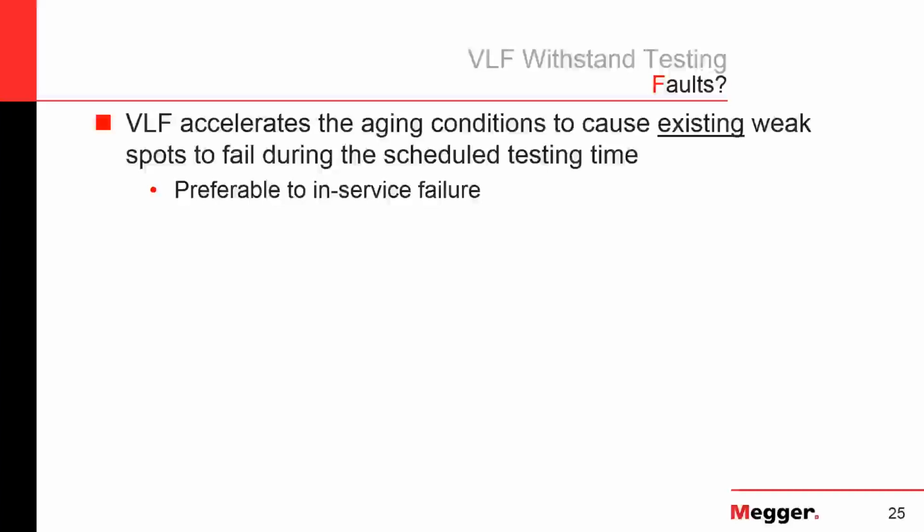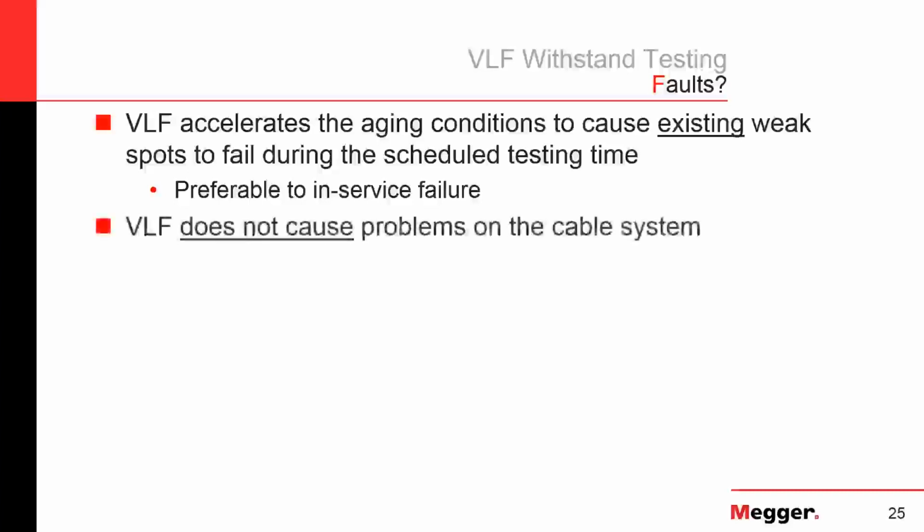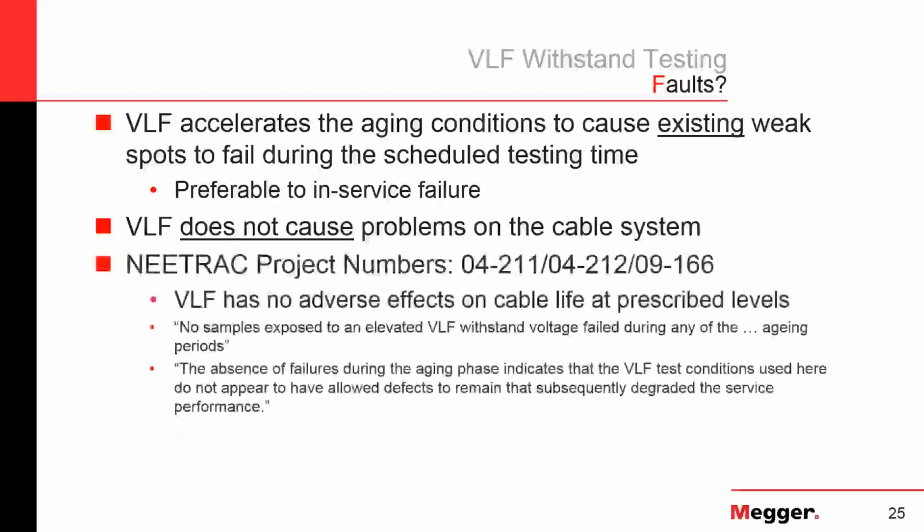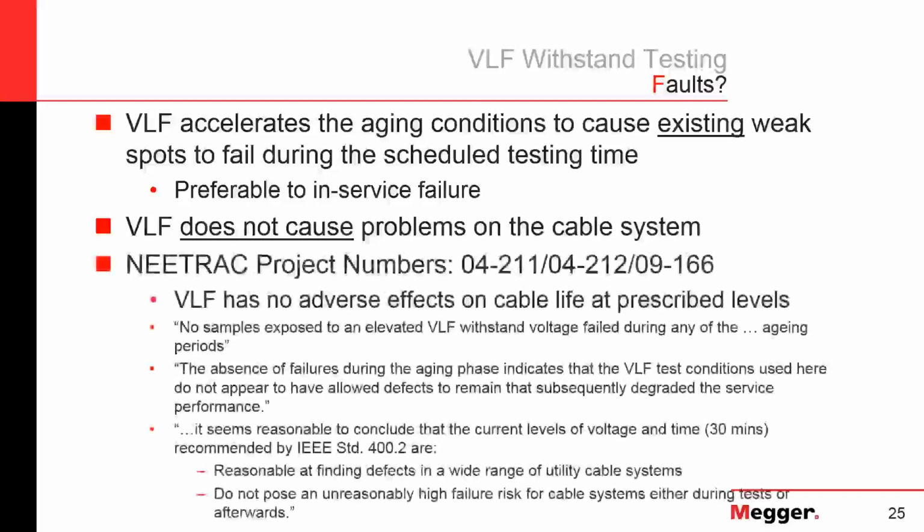Also, because of the power involved in a VLF test set, it's much lower than the power available from a substation, so your collateral damage is also a lot less. It's very often that a VLF test would fail and you only have to splice 1 phase, but if it failed in service, you may have to splice all 3 phases because of the damage to the adjacent phases. So it's important to know that VLF does not cause problems on the cable system. It only finds problems that are already existing.